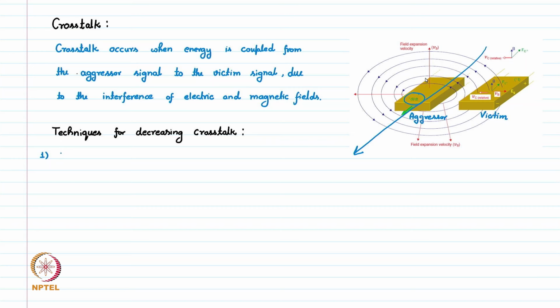So the first technique is increase the spacing between signal lines as much as possible.